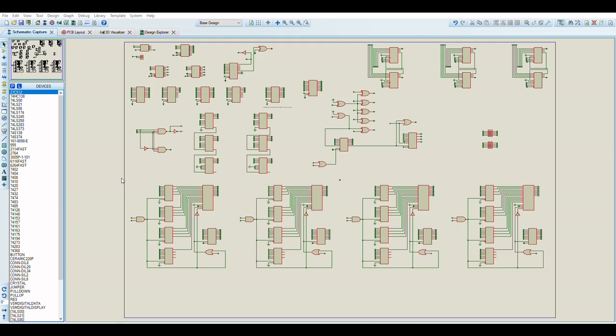I significantly expanded the hardware for the tile screen to accurately pixel scroll, but I also expanded its size. Instead of up to 8 separate static screens, I made it one huge, large virtual screen that can be scrolled around not just with pixel accuracy, but also in horizontal and vertical tile offset. Basically for free, due to the address memory line, you could scroll it around and it would wrap around.